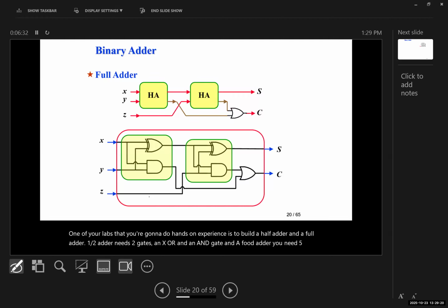And the magnitude comparator, the internal circuitry looks like this. You can see multiple NOT gates in the input, and you have the bypass for the working as a buffer to the AND gates. You're going to have 8 ANDs in the input and 8 NOT gates in the input. We're going to have 4 XORs connected to the AND gates, and then after that, you're going to have 7 other AND gates, and finally 2 OR gates.